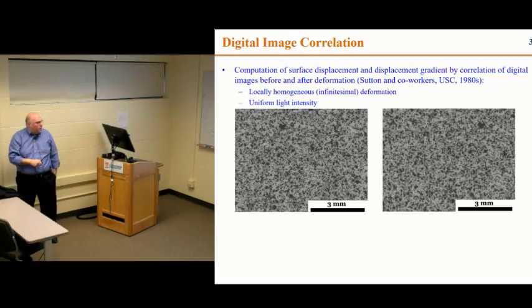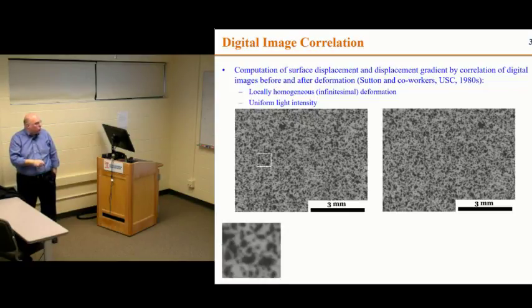And then once the deformation occurs between the initial state and the deformed state, because of either some loading, it could be mechanical loading, thermal loading, electrical loading in the case of the batteries, whatever. Something happens that changes the shape and the size of this object. You can then find this deformation by tracking where these particles go to. And you don't track pixel for pixel. That's impossible to do. So what you track is actually little subsets or groups of pixels, right? So you can pick a subset.